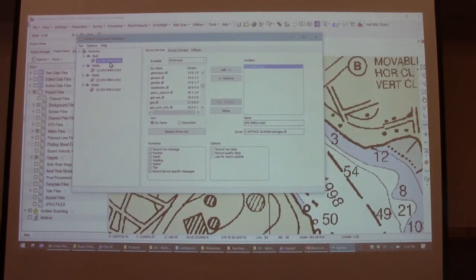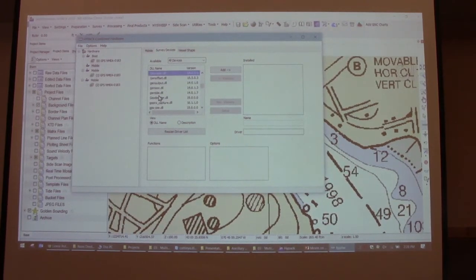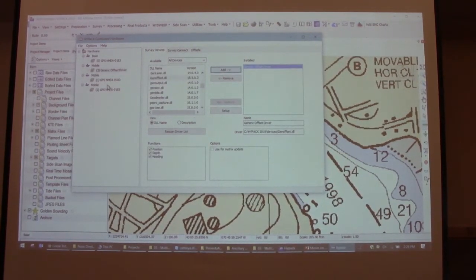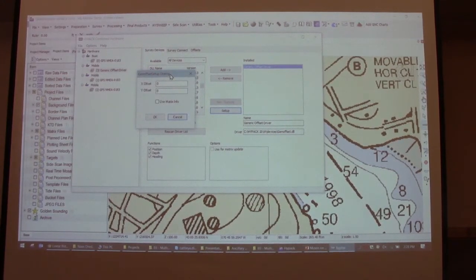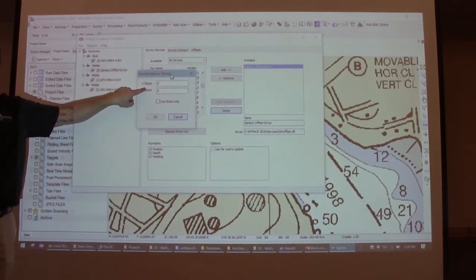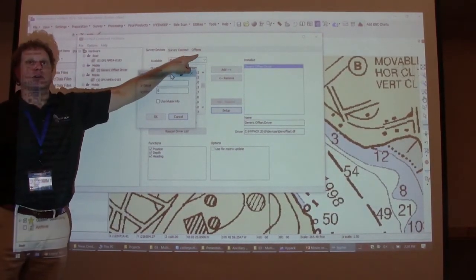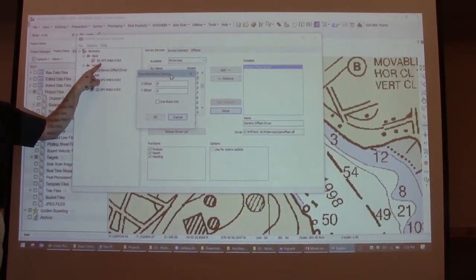So all those other boats can just have, and all you do is just give the offset for your transducer, not another GPS. Right. Each one of those boats would just have another fathometer transducer set up, and they would just be offset, because you're already collecting your data for the GPS in the first one. So in this case, I've taken this second mobile and I've replaced the GPS with a generic offset. And instead of entering the offsets where we normally do, I would give it an offset here relative to the position of the boat, and then that would put me a crosshair.